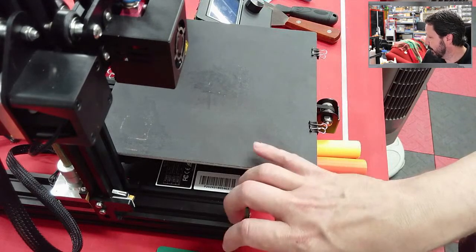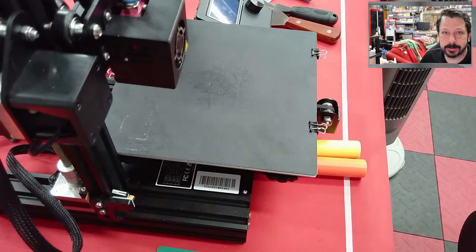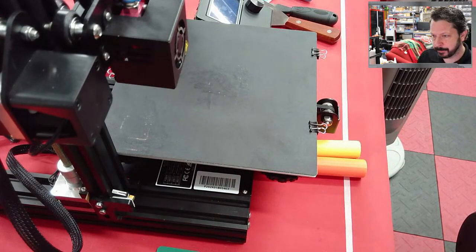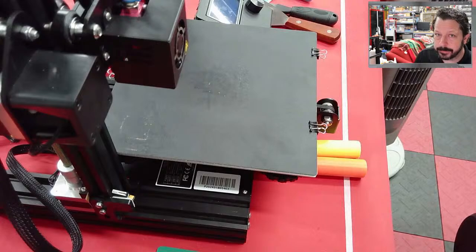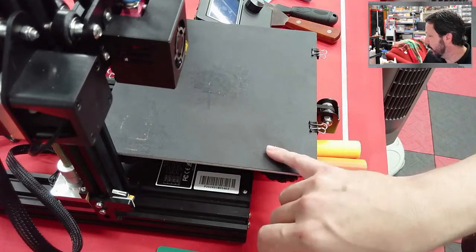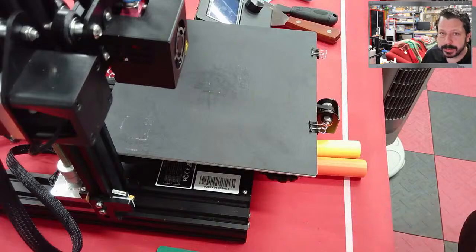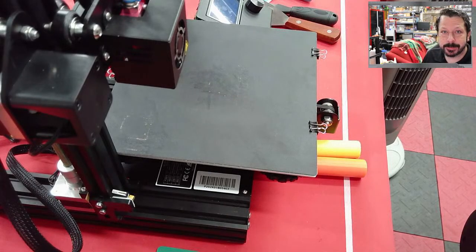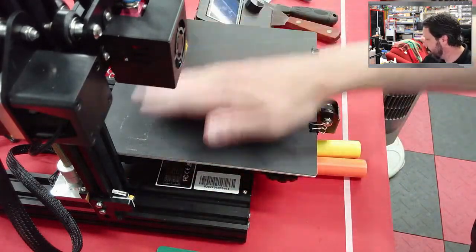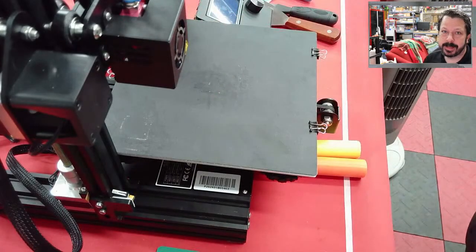The Creality glass bed has those dots on it. Those are similar, just a pattern of PEI dots on the surface. I believe they're PEI or material like it, and it will actually grab the part and hold on to it. Two cheaper alternatives to replacing the whole bed are to print on blue painter's tape. I don't have a piece of it out here right now, but I get the wider, 3-inch blue painter's tape and put that on the bed and then print on top of that.